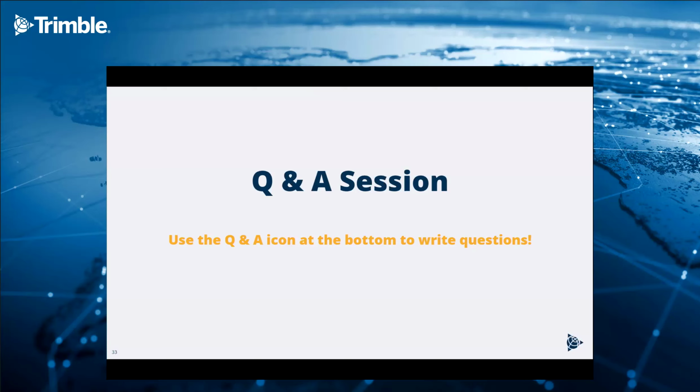And the ITRF frame realization is equal to the latest WGS84, but it's of higher precision because this is an international reference frame, which is not only based on GPS observables, but also on other satellite navigation observables. And we output always in the latest international reference frame, which is the ITRF 2020.